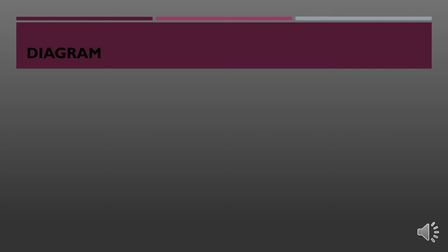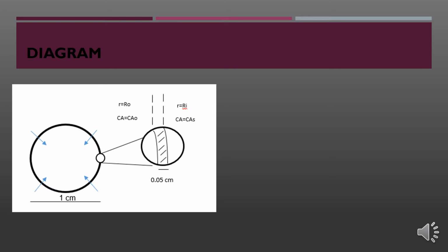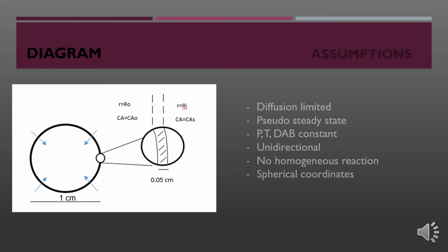In order to solve this problem, it's necessary to explain what is happening. This is a problem of steady-state molecular diffusion, as it was mentioned, and it operates in a simple system in which the concentration and the mass flow are functions of a spatial coordinate that is spherical. We can assume that the pressure, temperature, and diffusivity are constant. Also, the concentration is limited because the biogranule can only absorb a certain quantity of the solution, that is the contaminated water and the ethanol.